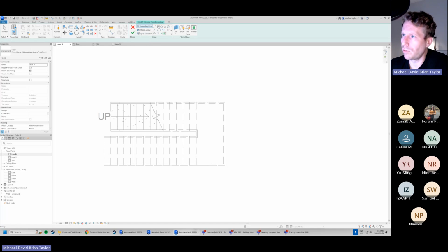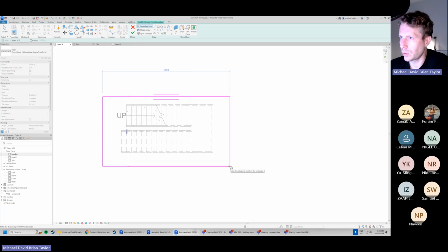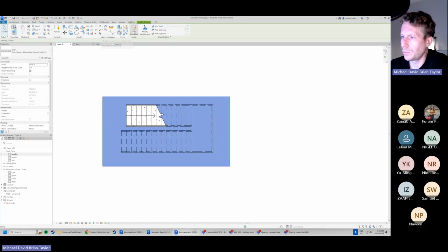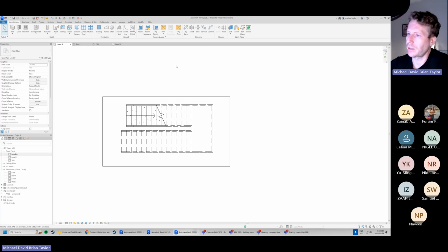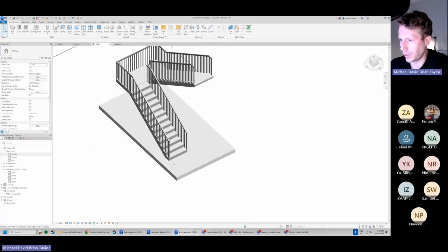So we'll generate one floor. Doesn't need to be any particular size, but let's just draw a little rectangle. Remember, in our draw panel, we're just going to draw a little rectangle, click once, click twice, just a little floor. Just finish the sketch by clicking our little green check mark. Boom. We should see something like this, and this is our starting floor, right?